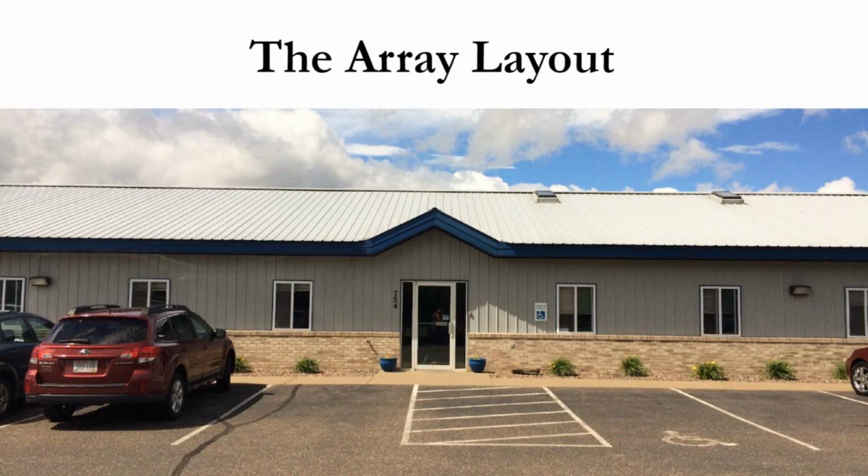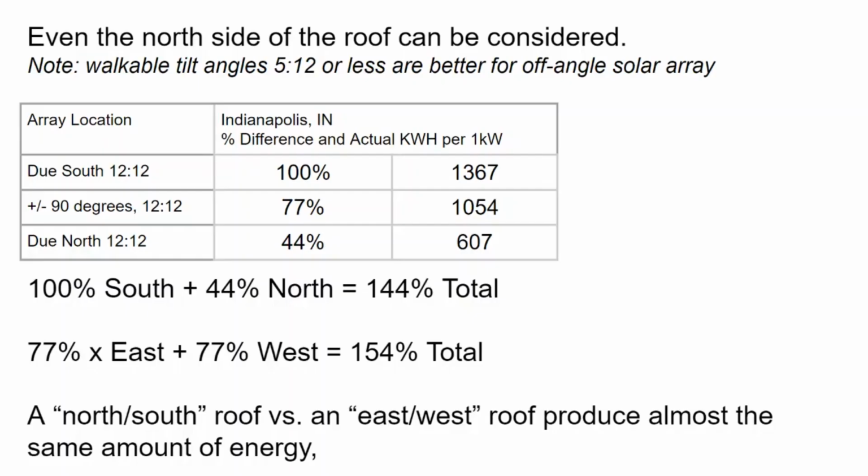It should be obvious that a good solar job site is one with large open surface areas with access to sunlight. While partial shading can be designed around, the whole point of solar is not to be in the shade. In the PV watts section, we learned that an east-facing solar array will produce 15 to 30% less than a south-facing array, depending on the tilt angle of the roof.